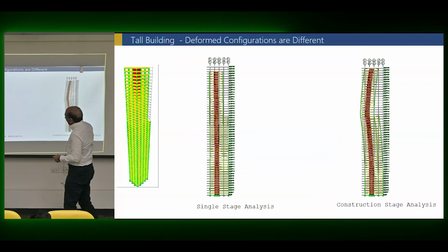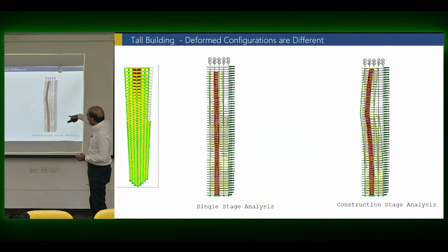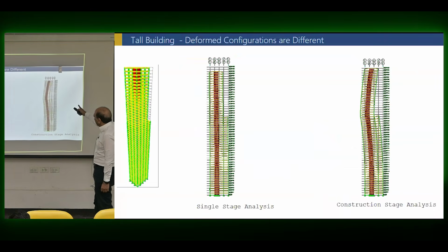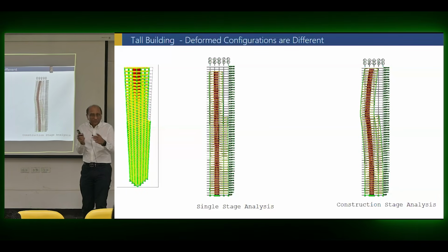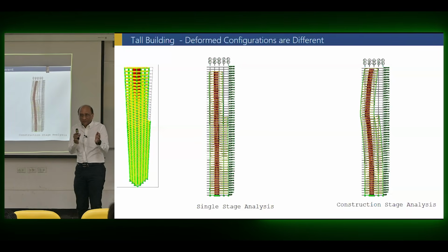And this is an old slide I dug up a long time ago. And you can see here that tall building and this tall building, how it shows the deformed shape just for gravity loads. So this will be how the building will act, because they will always try to make it correct, but the building will keep shifting. Below that, they cannot have a control, but every floor, they will bring it back.